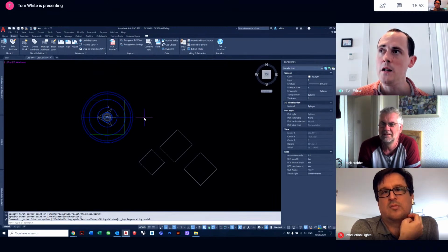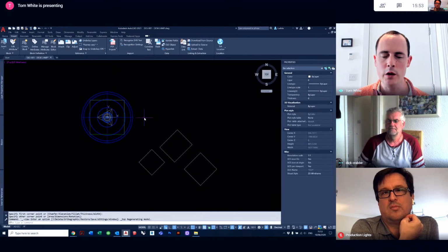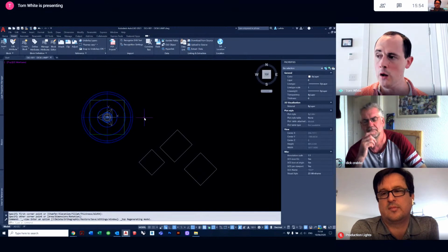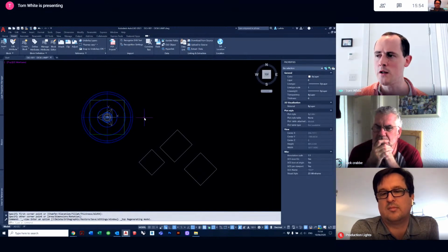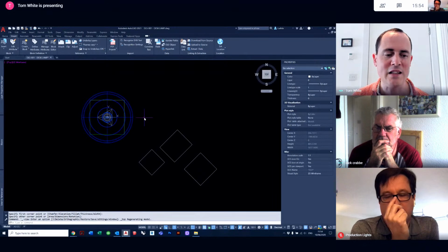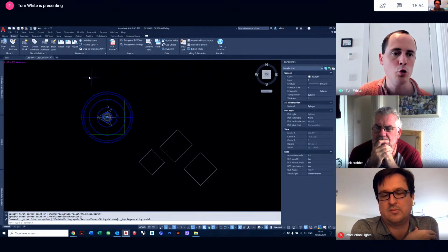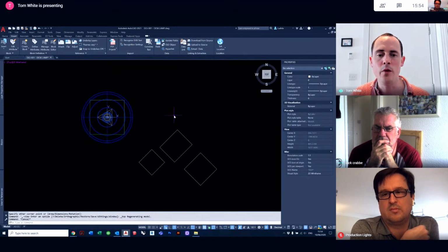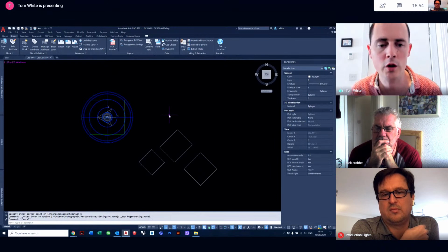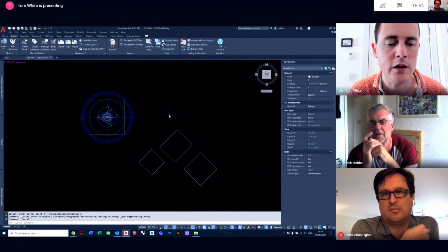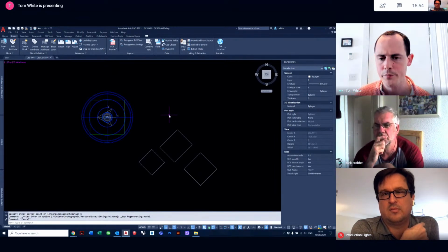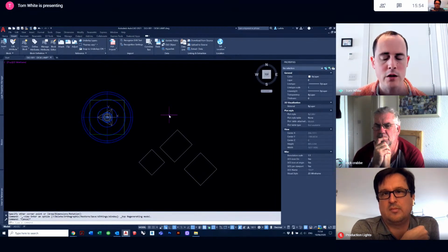In a scenario where you open a drawing and bring an XREF in, and for some reason you think, oh gosh, that looks a bit different, I'd recommend detaching the XREF entirely, going to top view or world UCS, changing the UCS to what you think might be the world coordinate system, and then re-bringing in the XREF to see if that solves the situation.